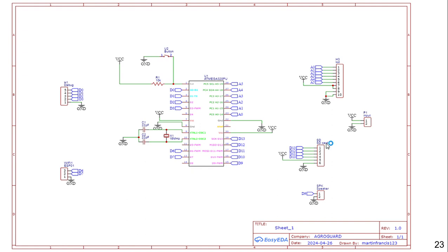Ninth pin will be used for taking out the audio received from the SD card and giving the audio to the amplifier module. Now pins from 23 to 28 are used for our LCD, because for our LCD module we will be using analog pins here because of the limitation of digital pins. Since analog pins can also be configured as digital pins, we can use these pins, and it will work. So that's the overall design of the system.